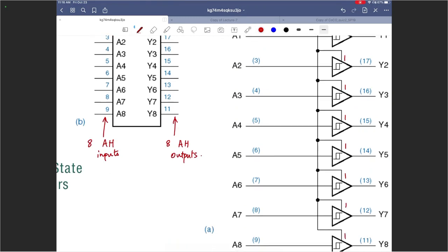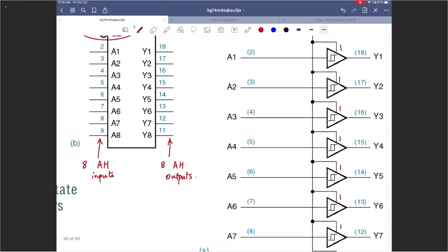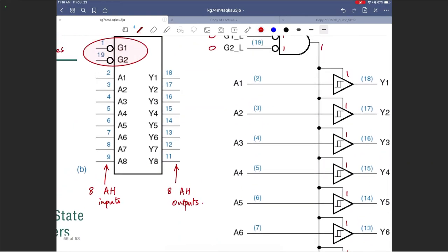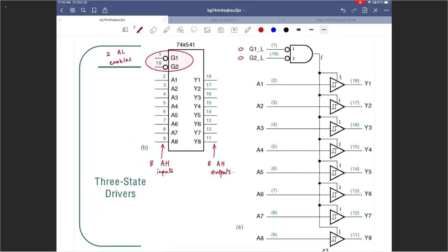These are tri-state buffers that are using Schmitt trigger technology, right? So these are 8 tri-state buffers that are operating on Schmitt trigger technology, which essentially means I have an upper threshold and a lower threshold, so I can ignore some of the noise that is around 0. We talked about that when we had the Schmitt trigger discussion. But it's essentially a buffer.